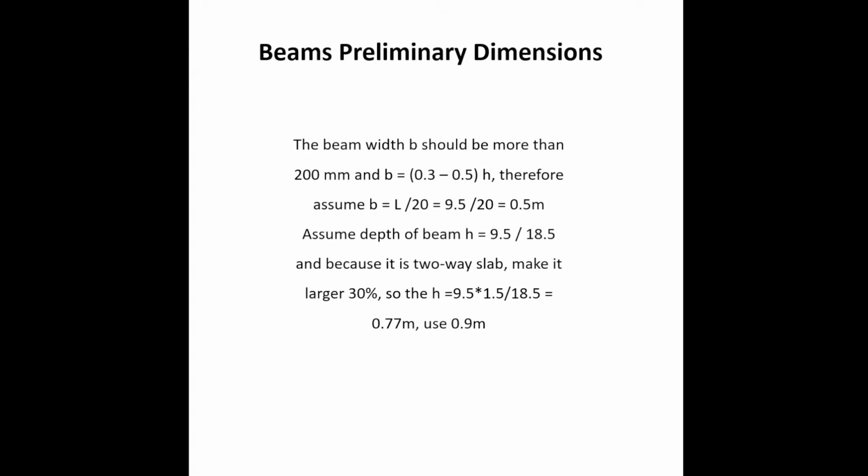But to avoid the problems related to deflections and slab thickness and so forth, we need to increase the depth for the main beams, to make them stiff enough. So you know, the alpha m, which is in the ACI code, is related to the moment of inertia of beam over moment of inertia of slab.